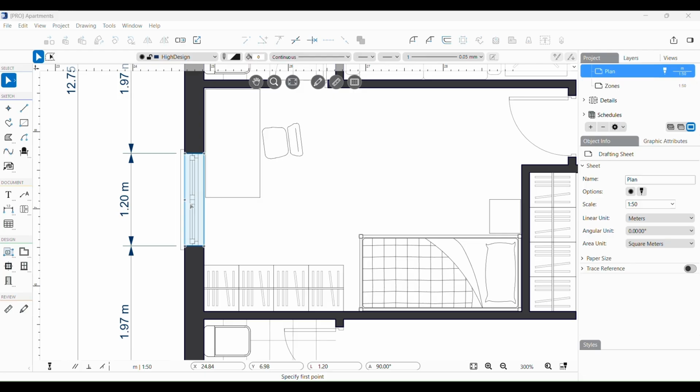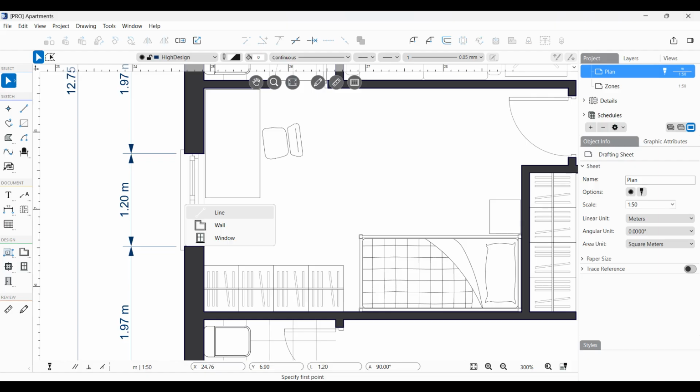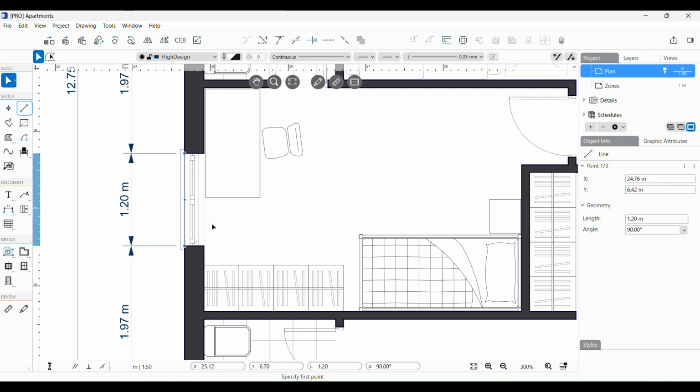Selecting overlapping objects. When two or more items overlap, it can be difficult to select the right object. To get a smart selection, activate the arrow tool, hold the Control key, and click or right-click on the intersection to open a contextual menu with a list of all the objects at that location, from top to bottom. Choose the item of the list you actually wish to select.